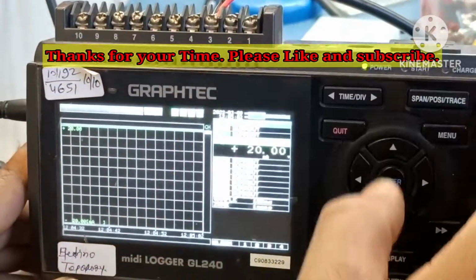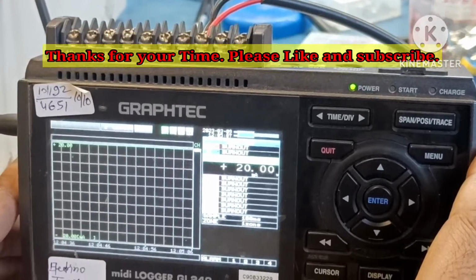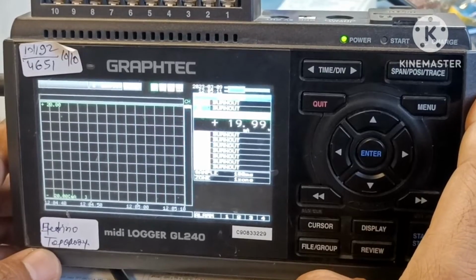Make sure you connect the 250 ohm resistance, so that it will help you measure the reading in the data logger by using the engineering unit.